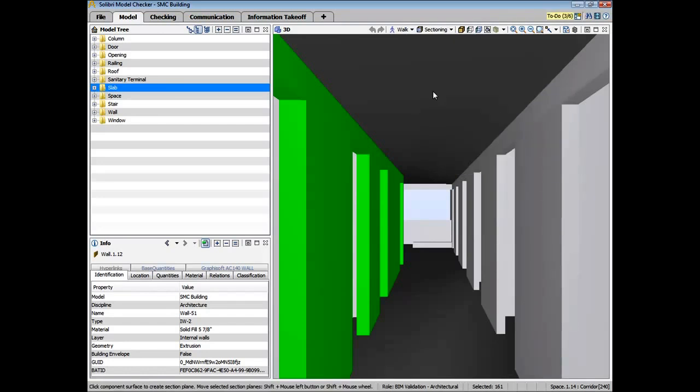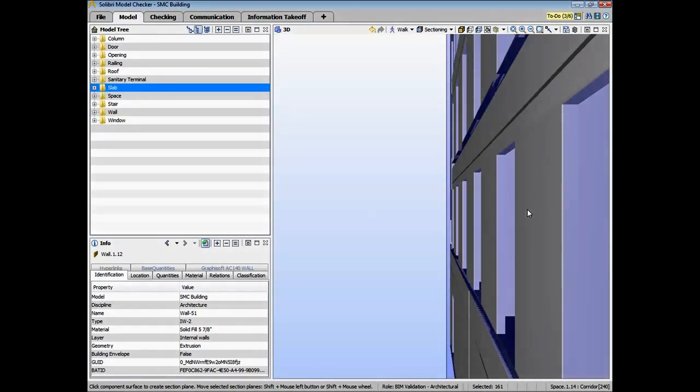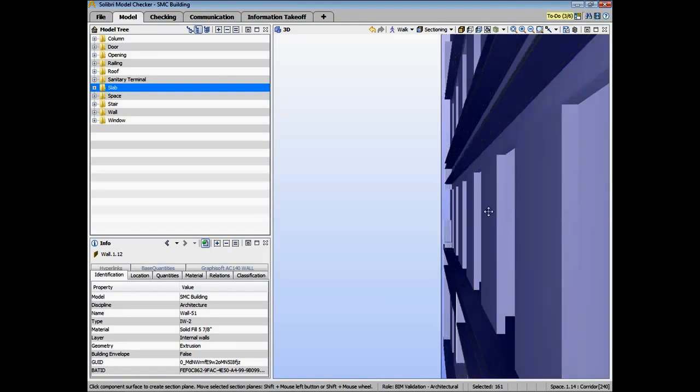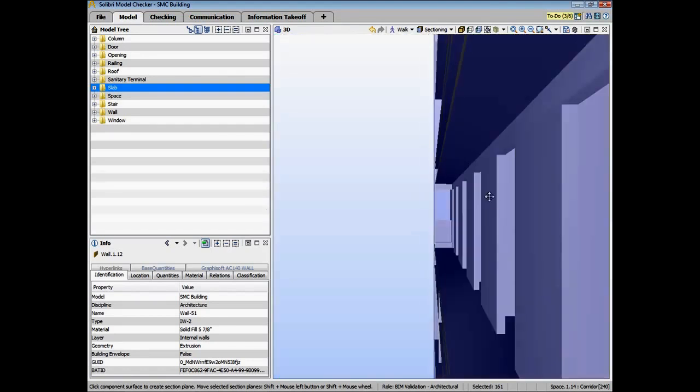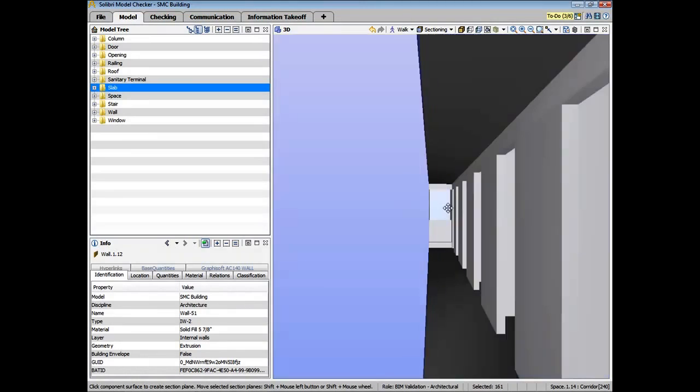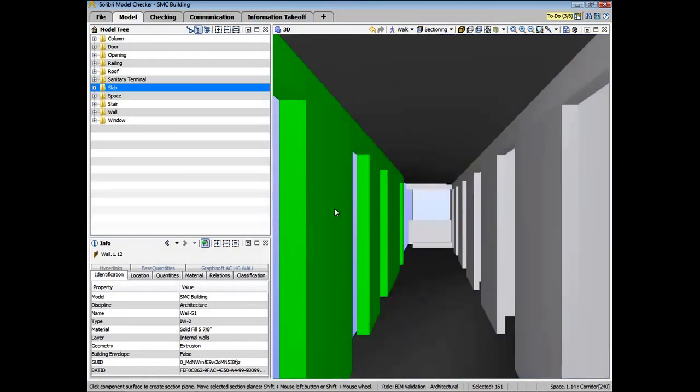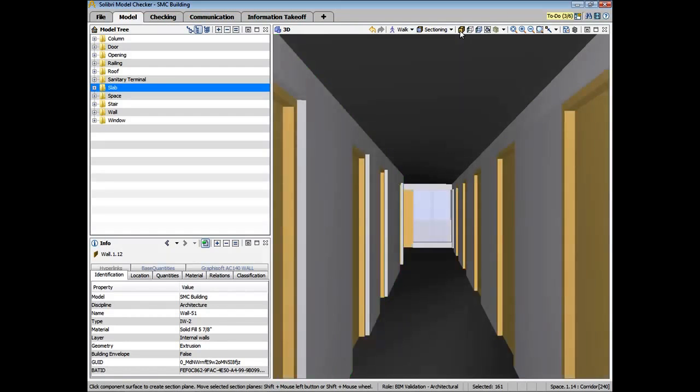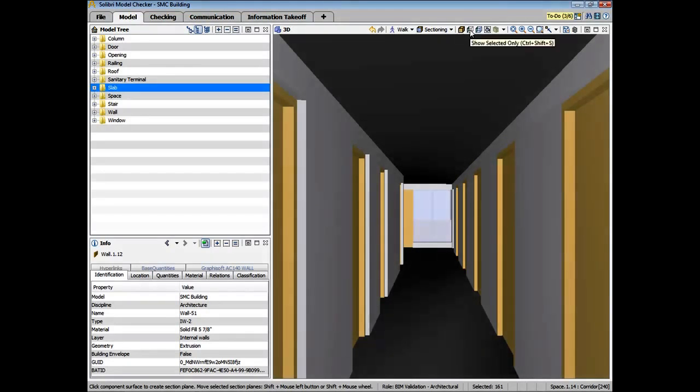Let's use this surface plane to make the section, so we'll switch to a sectioning mode. And you're able to change the sectioning by pushing the shift key. We select our original plane that we want to use as the sectioning plane, and then we can adjust those using our mouse and shift buttons. If we again want to go to a completely visible model, we can just choose the Show All button. With Selected Only, you basically get what you have selected earlier, and everything else displays as transparent components.